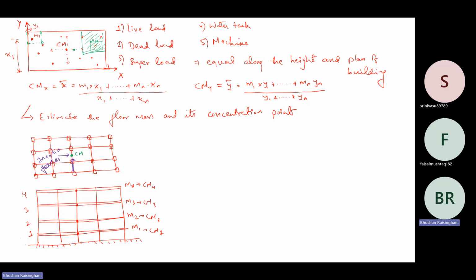calculating the floor mass, and you will give this as X, you will give this as Y, and you will estimate X1, Y1 for however many masses there are, right? You will get the mass, you will get the coordinates. From that, you will get the center of mass. And this is the point where the earthquake forces or the lateral forces will get applied.